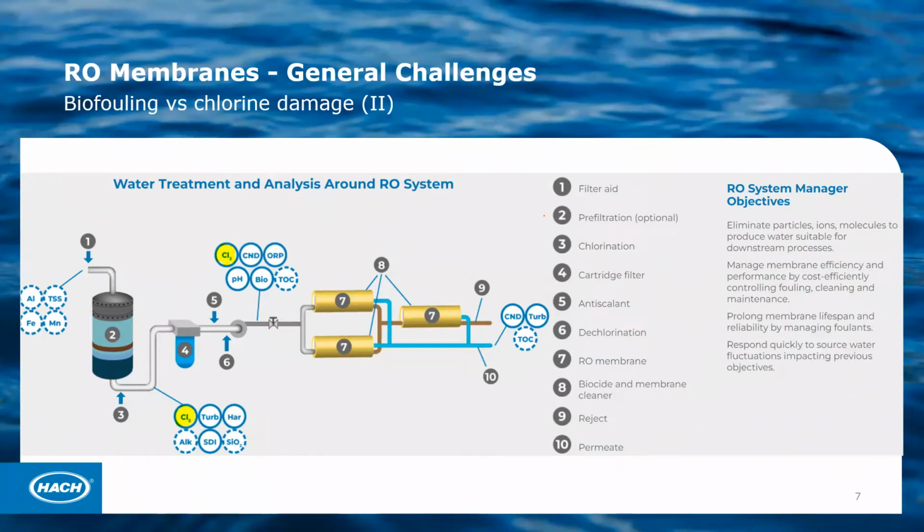And so we would typically measure, you can see after stages 5 and 6, 6 being where dechlorination happens, we would monitor perhaps chlorine, pH is important, of course. If we didn't have a chlorine analyzer in place, maybe we're using ORP as a proxy measurement to gauge where our oxidant levels are. But I just wanted to show where we would typically recommend that these type of measurements take place. So after dechlorination is really what we're talking about focusing on with this solution here.